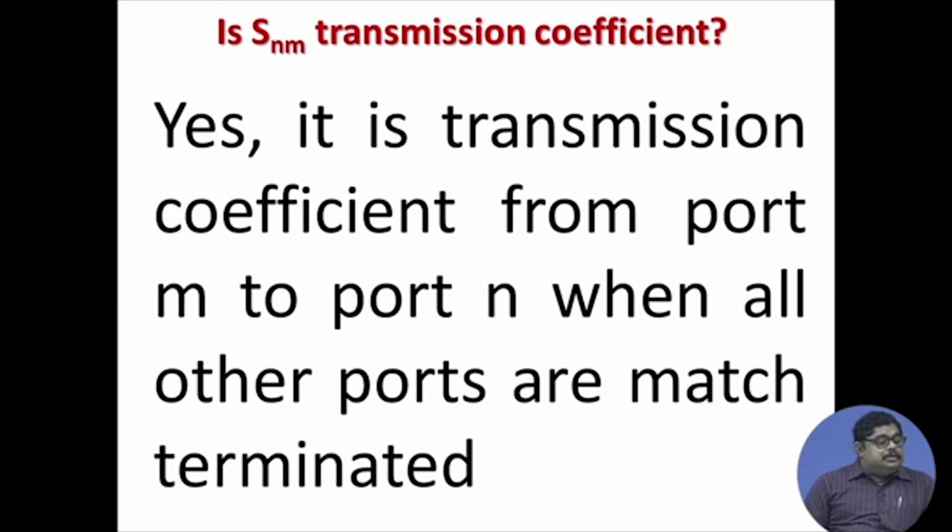Is SNM a transmission coefficient? Again our answer is yes or no. So, it will be yes when it is the transmission coefficient from port M to port N when all other ports are match terminated. So, this match termination is important, other ports match terminated, then S parameter SNM is the transmission coefficient.